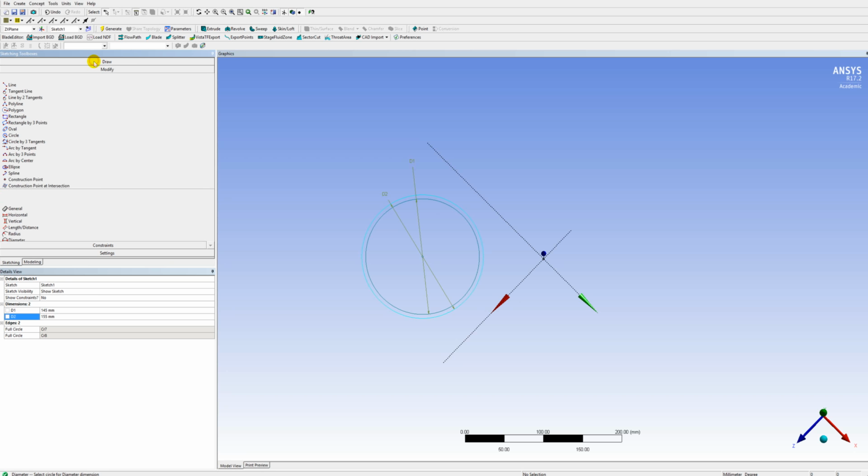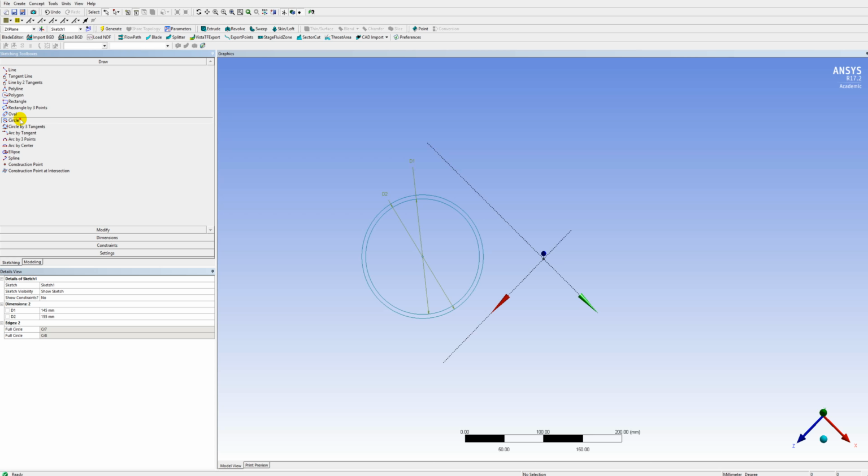And now we want to draw 2 more cross sections exactly like that. And you can do that without redimensioning the other cross sections. And how you do that is you click away from the first circle so they don't overlap. You click to place the center, and you slowly move out until you see a little R appear. See, there we go, there's our little R.